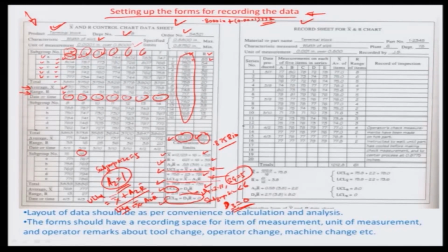Now, you just have to draw the mean value, the upper control limit and the lower control limit, whether it is the range chart or the X double bar chart, and these two charts are typically plotted graphically on one paper. Then all you need to do is take your subgroups of observations beyond this period. This period has been used as the basic period for calculating the control limits, but beyond it the production continues.